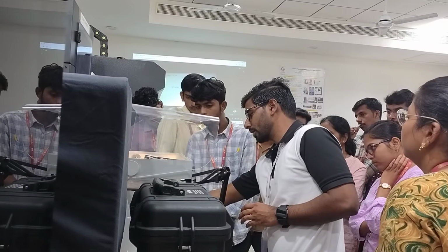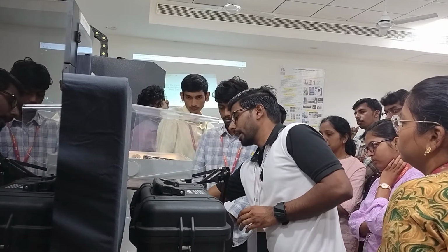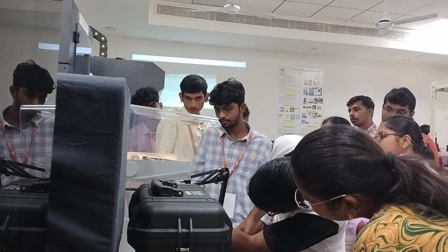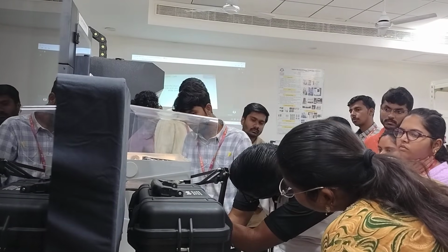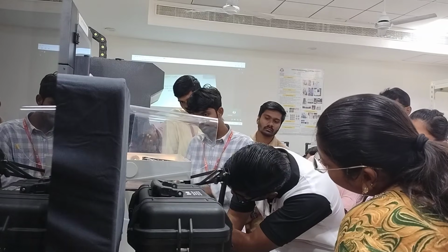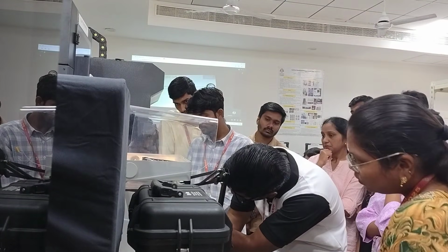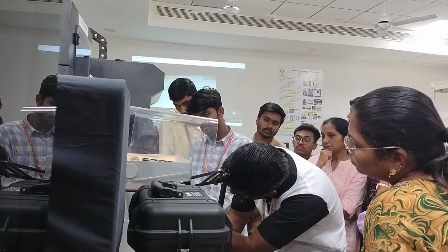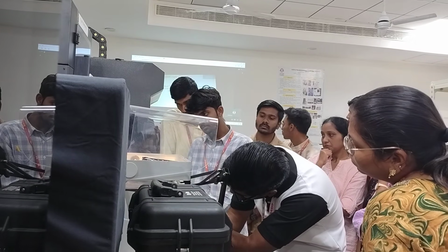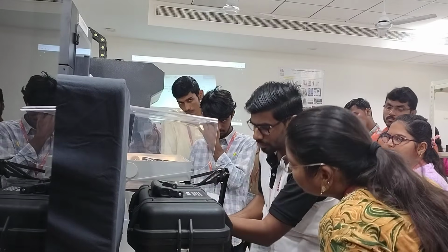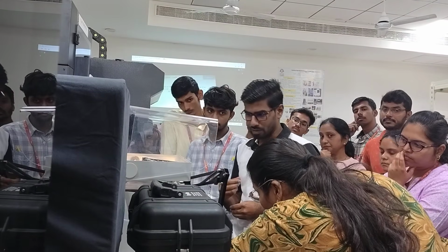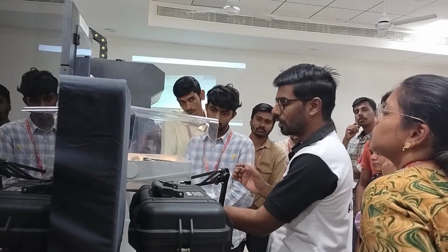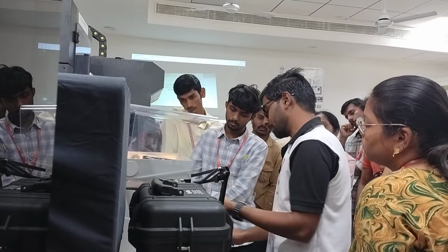It is moving to the right position, left position, sorry. Again, we'll do the same thing here also. I'll put it between the nozzle and the bed and I'll screw it. I'll continuously move it so that I get the exact clearance. One of you can just move it and see if you're getting some resistance. There is some resistance, right? That is the resistance we should have. It should not be very tight, and it should not be very loose. Then I click on next.